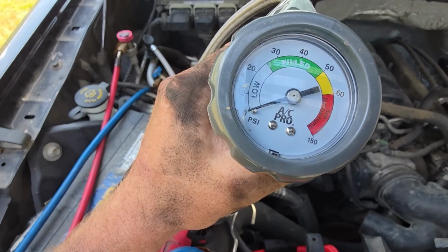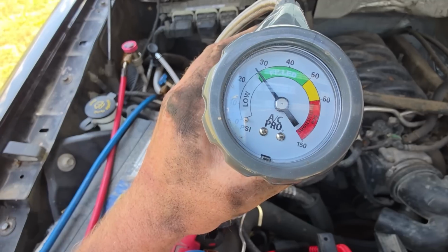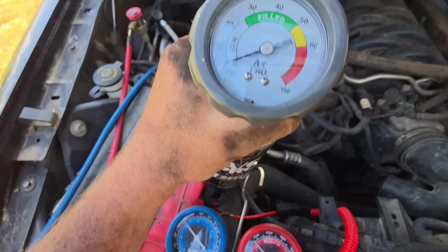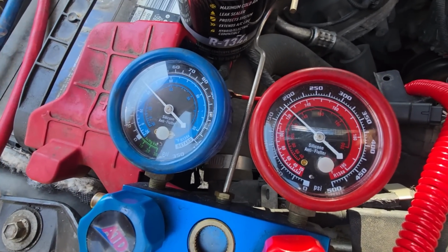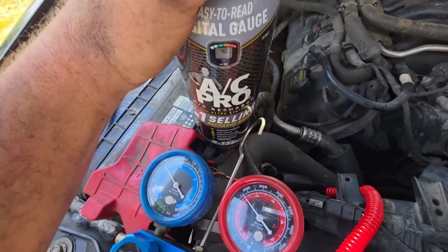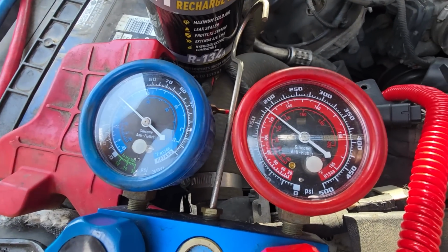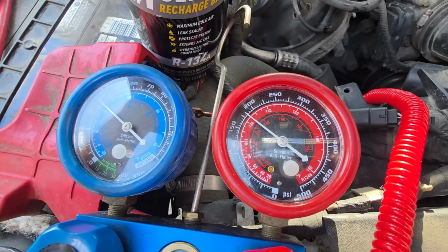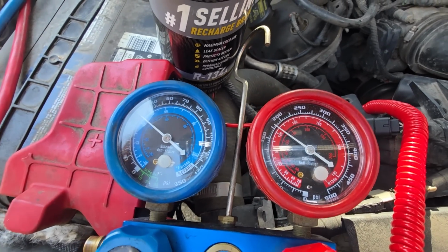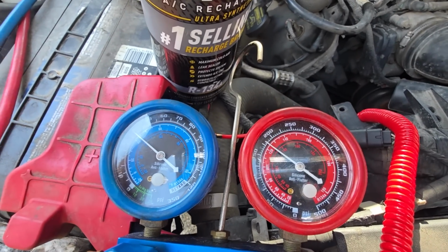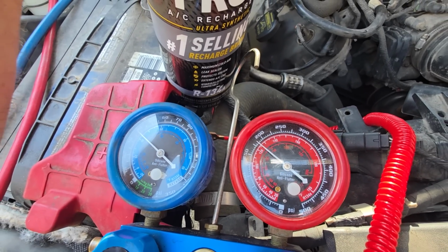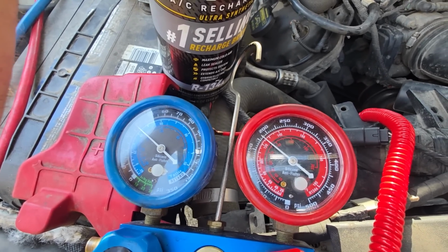It reads low on there with the trigger pulled. Let go of the trigger, gives you a gauge reading, about 25 psi. But I'm watching high side as I'm doing this. It's taking a while, again, because I'm adding as a vapor with the can straight up and down. Day like today, 1500 RPM, fans running, 90 degrees with a 70-degree dew point. Yeah, I'm totally fine with like 2.25, maybe even 250 on the high side.